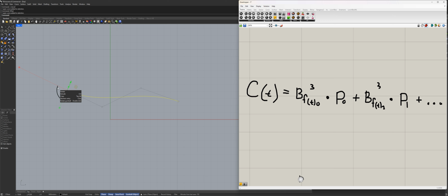Everything else has some control as well, but it diminishes the further away it is. And basis functions basically define that. They define how loud the point is supposed to be along the curve between the control points. And this position between control points, at which the loudness is whatever it is, is defined by this value t.